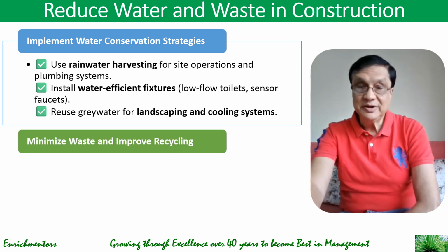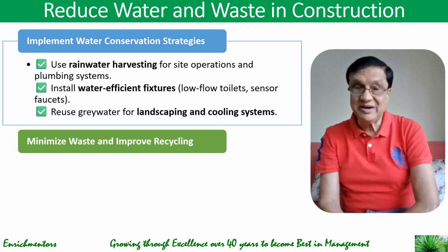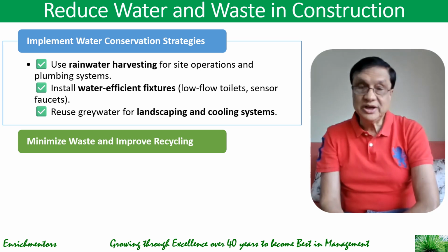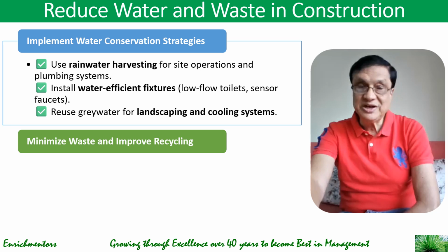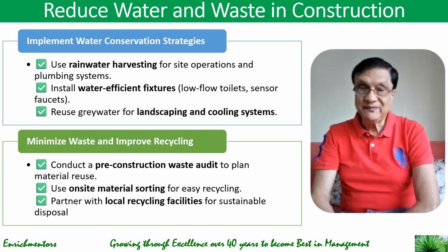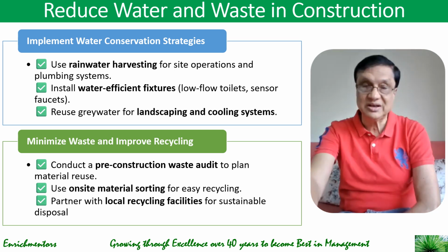Then another thing you can do is to minimize waste and improve recycling, as I was saying. So, what can you do for that? You can plan material reuse by conducting a pre-construction waste audit to plan material usage. And for easy recycling, use on-site material sorting, and for sustainable disposal, work with local recycling facilities.